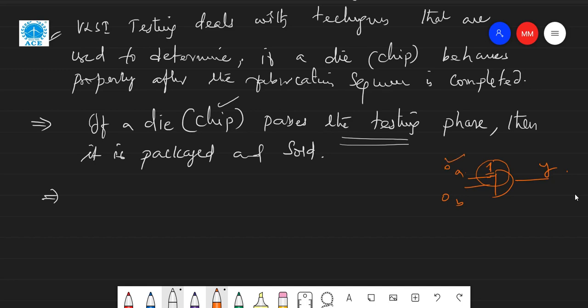Instead of a 0 input, I am getting 1 as the input, so the output changes. By giving the inputs, the output varies. We need to understand these faults as manufacturing defects. We designed the particular circuit properly, but while manufacturing, due to the etching process of vias or mismatch of connections, the output changes.